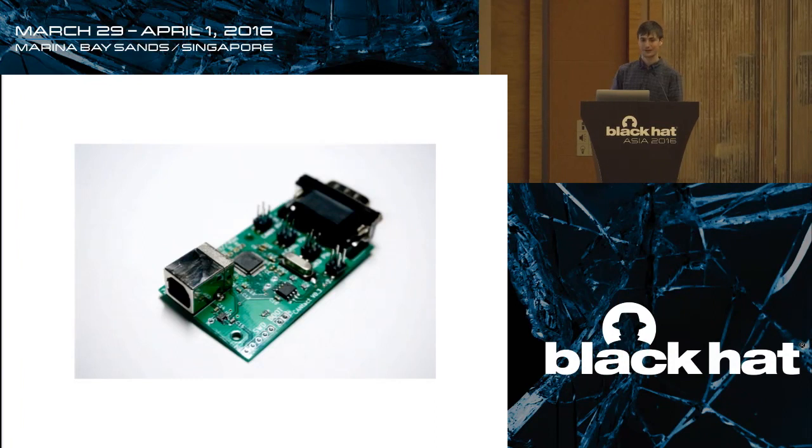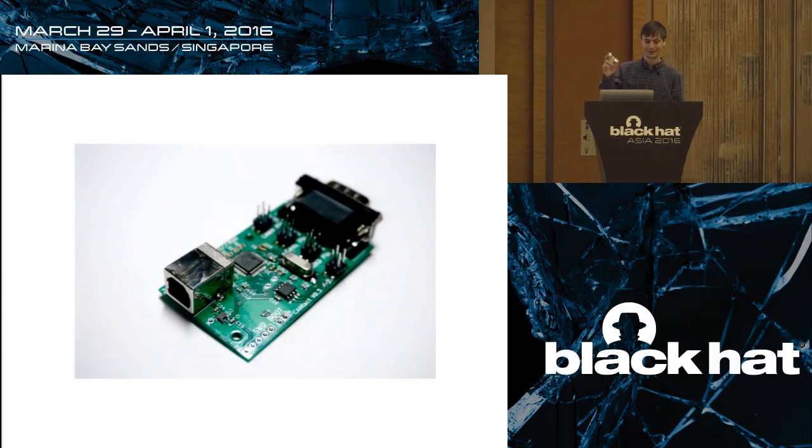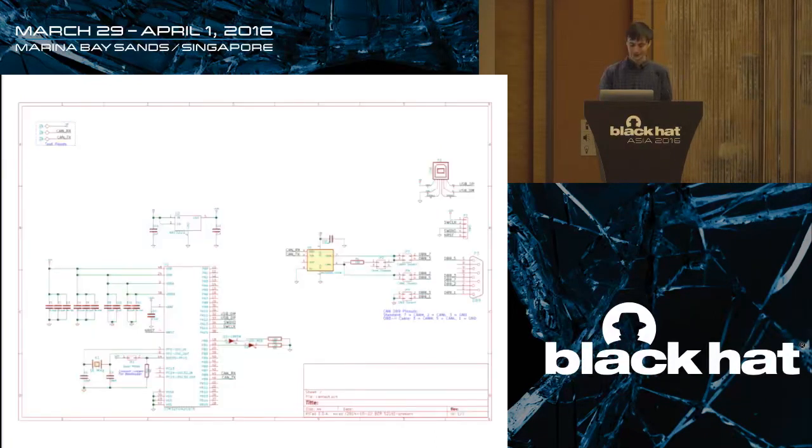So there's a big picture in case you can't see it here. You can come take a look at it later, of course. And the schematic, it's really simple. Like, there's a microcontroller, some supporting lots of caps to filter it. There's an LDO for voltage conversion from 5 volts on USB down to 3.3. You have the CAN transceiver, CAN high and low, jumper selection.